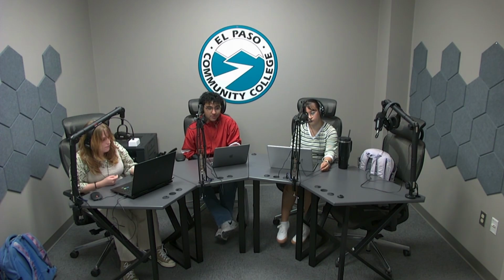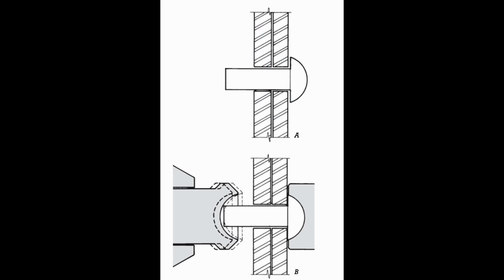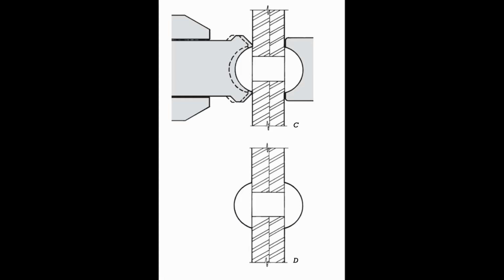So moving on to rivets. Rivets are steel fasteners consisting of a cylindrical body and a formed head. As seen in part A, a hot steel rivet is inserted through the holes in the two members to be joined. In parts B and C, its head is placed in the cup-shaped depression of a heavy handheld hammer. This hammer then drives the rivet sets repeatedly against the body of the rivet to form the second head. And then finally, in part D, the rivet shrinks as it cools, drawing the members tightly together.